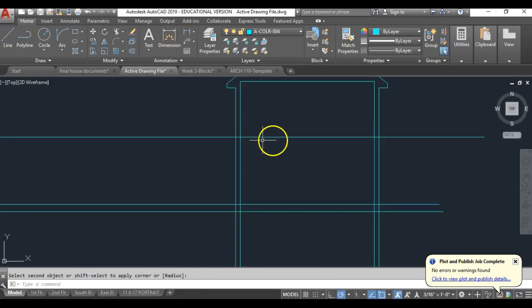And we can do the same thing to get the second floor thickness. The floor to floor for the first floor, if you look at your drawing, is 9 foot 0. So that's this line here. So I'm going to offset 9 foot and select this line and click here, and we can see the result is what the floor thickness is going to be.